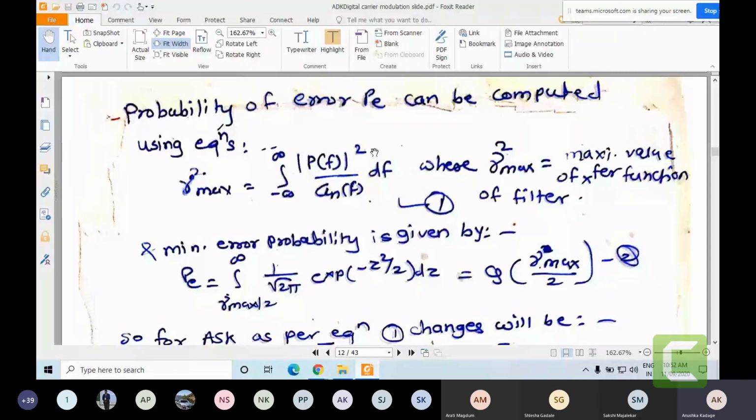And this probability of error is going to lie with the Gaussian probability density function, and for this Gaussian probability density function, the sigma square, that is variance value, will be equal to 1, because ZT will be always having the output average value which is equal to 1, and that's why here the sigma square in original Gaussian PDF equation will be substituted as 1 in under root position, and also in this denominator position multiplied with this 2.